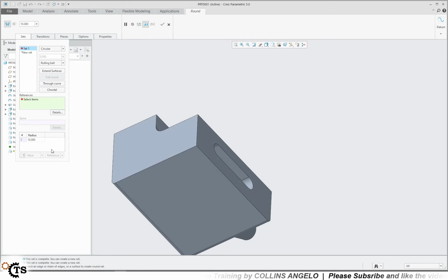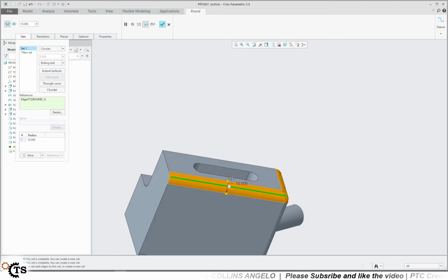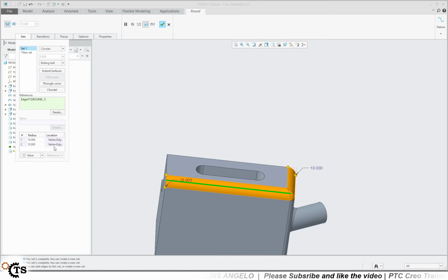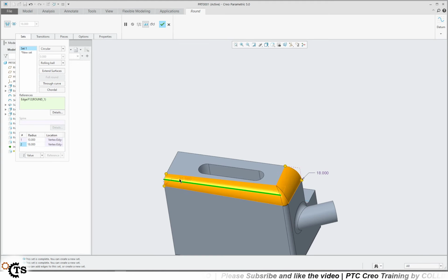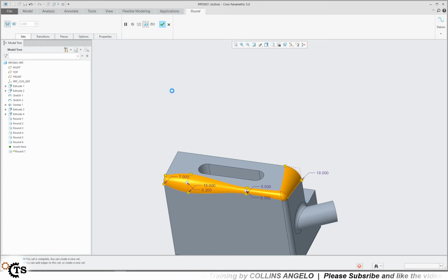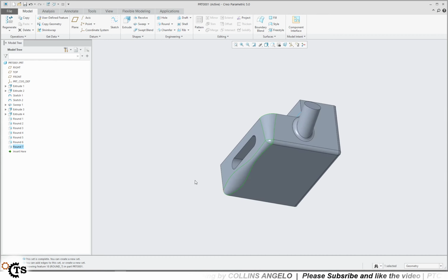Another important thing is regarding multiple radiuses. For example, you have this radius picked here and you want to define more radius, so you just right click and add radius. By doing that, you can define variable radiuses. So if you want a small radius here, you can do that. Not just 2, you can add multiple radiuses. So this one can be 15, and I need one more, which is maybe over here. You can just click this, drag it to the position that we want, and maybe this is 5. So that's with the multiple radius.